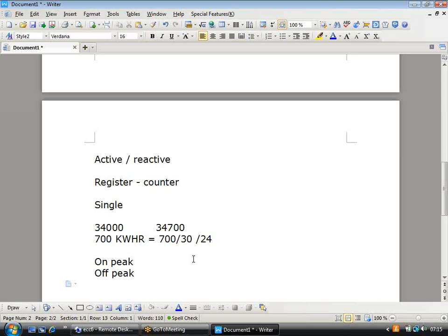So when you create a device category, how many counters are there? How many registers are there? And for each register, what data will apply? Is it for electricity, water, or gas? What is the output you are going to measure? Is it a 5-digit number or a 4-digit number? Is it going to measure active energy or reactive energy? Should the register be used for billing? All these data will be maintained in the register group.